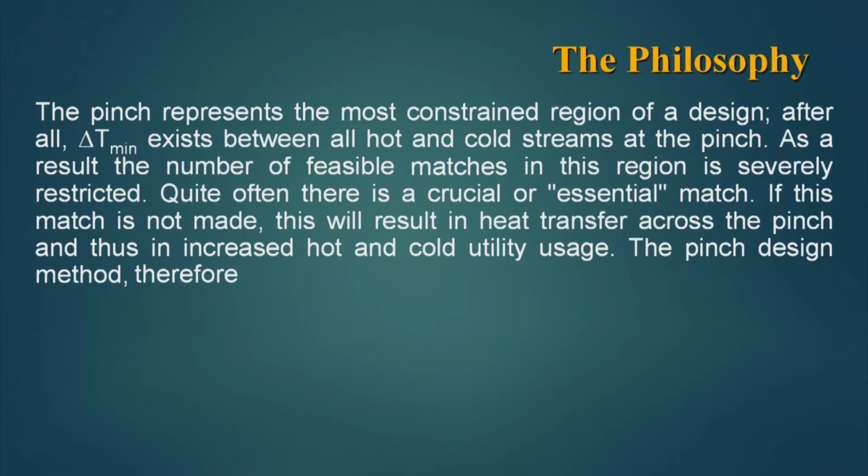As the delta T minimum is small, the heat exchangers which operate near the pinch or at the pinch operate at minimum temperature difference, and hence the areas of these heat exchangers are mostly large.